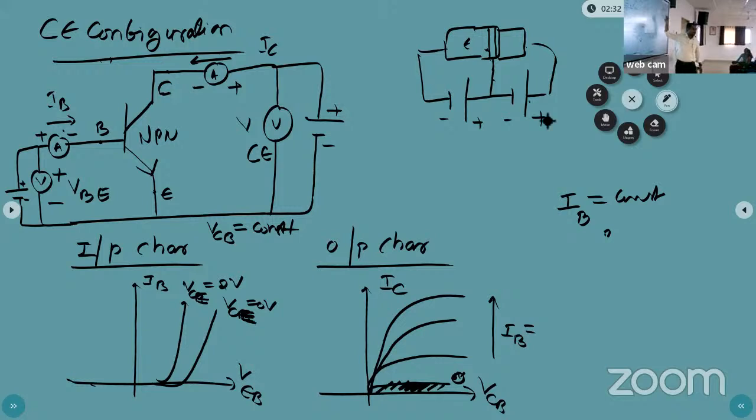Reverse bias. So now in this region, both the emitter diode and the collector diode are reverse bias. If you apply 0 input current, the input bias, that is the emitter diode and the collector diode, this junction and this junction, both are in reverse bias.